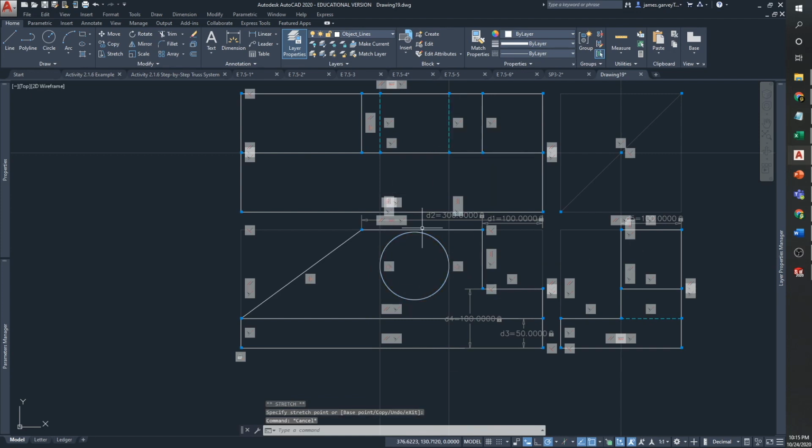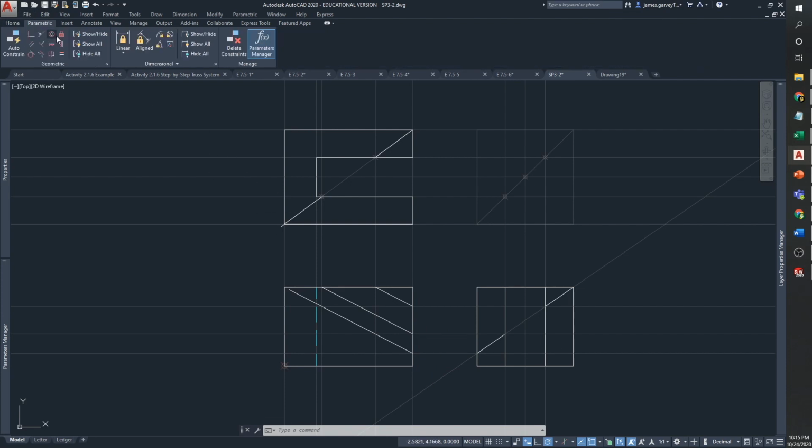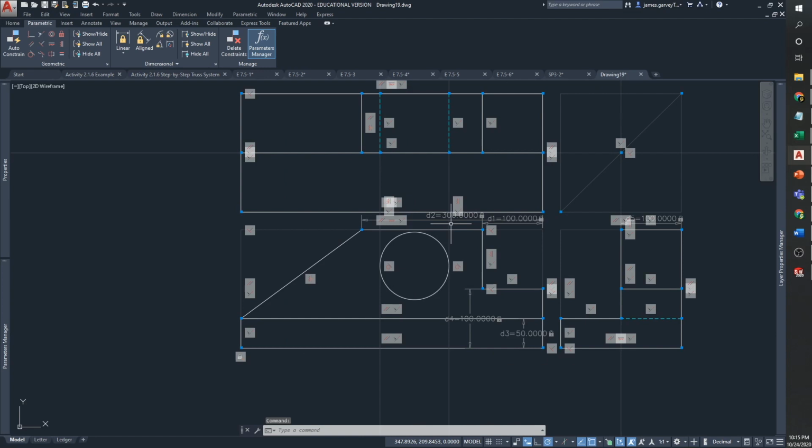So I would do the same thing for the right view, put the construction lines, auto constrain it so I get my tangent and vertical on there, put my lines in, get those collinear to it, and it should always match up. The one I'm having you run through has those oblique surfaces, so make sure to match your points up, using construction lines, or even going through manually and adding a horizontal constraint between this point and this point so they move together. It shouldn't take too long, but it is a little more complex than the one I just ran through, but not terribly so.